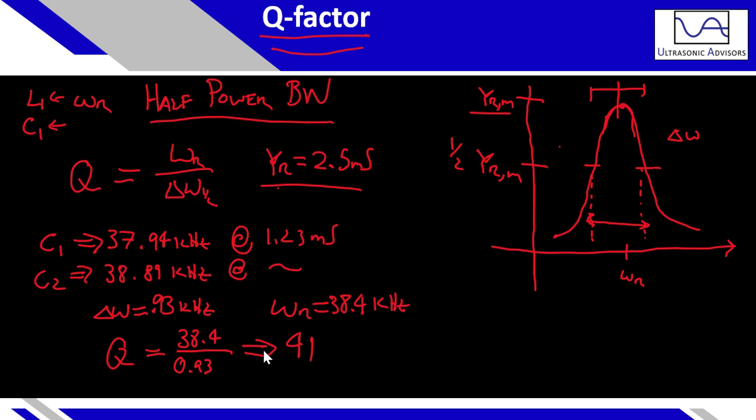So this is the method and methodology to calculate the quality factor, but it still doesn't directly give us an L or C value. The quality factor, by its definition, is related to 2 pi times the frequency, obviously the resonant frequency in this case, multiplied by the energy stored per cycle divided by the power dissipation rate.